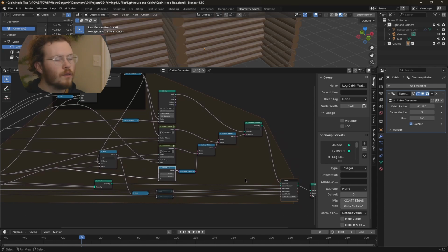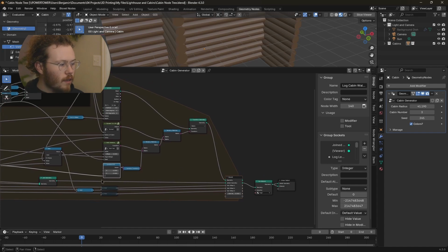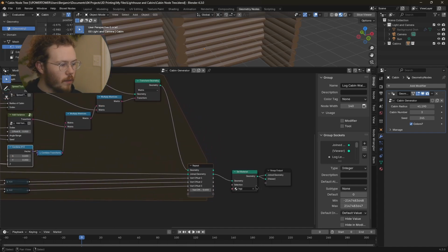through a few times. So what that's doing is that when log is placed, it's a random diameter. So then it comes around, places 3 more logs. When it comes back to that first log, if we just use the standard consistent offset, it would intersect by a random amount. So what I'm doing is I'm storing that value and using it later as it comes through these offsets, so that when we come back to place the log on top of that first one, it will be the proper offset higher. So that's just a way of tracking that and getting it to iterate properly.